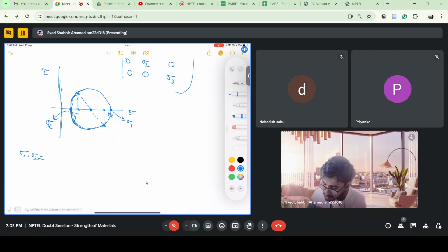If I want to find sigma 1 or sigma 2, I can first find the midpoint. I have 2 points on the x-axis, sigma x comma 0 and sigma y comma 0. These are the Cartesian coordinates of these points. So I'll first find the midpoint of these 2 points, sigma x and sigma y, which is (sigma x plus sigma y) over 2. And then I have to find this radius, right? This is the radius of the circle, and this line is also the radius, right?